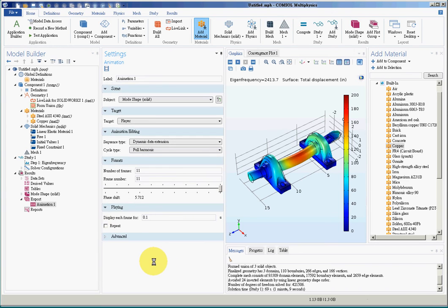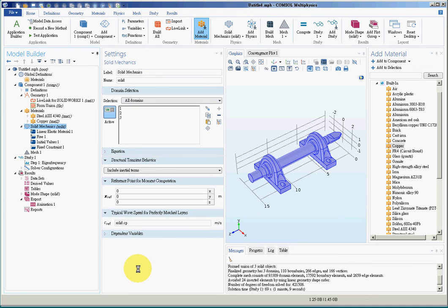So this is the eigenfrequency analysis in COMSOL. In COMSOL, it is called eigenfrequencies. Theoretically, it is called natural vibration, and in, for example, ANSYS, it is called modal analysis. So generally, we don't place any external load on a natural vibration problem,